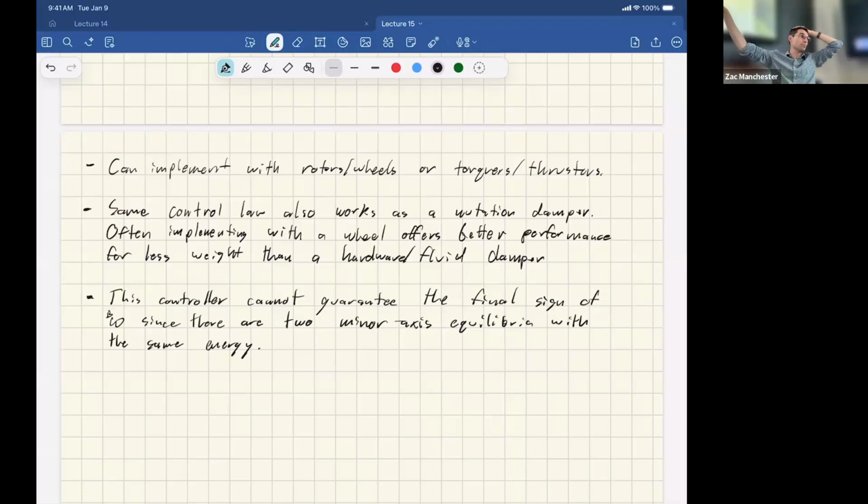Here, it's the opposite problem. This is underdetermined. So I have an infinite number of possible U's that can generate the desired torque. So it's the opposite problem. I can solve this exactly, but there's no unique solution. There's a whole bunch of U's that would generate the desired tau. So I have a different problem than the least squares problem. Annoyingly, I still call it a pseudo inverse, but it's a totally different sort of object